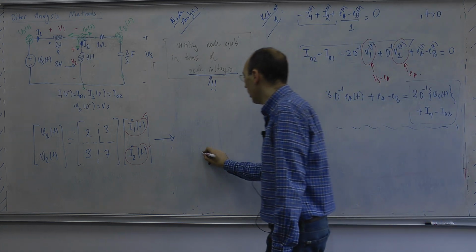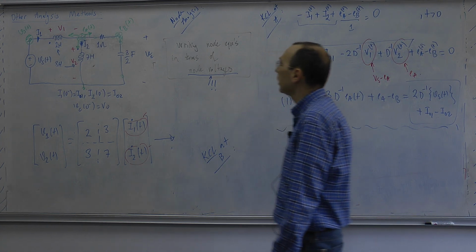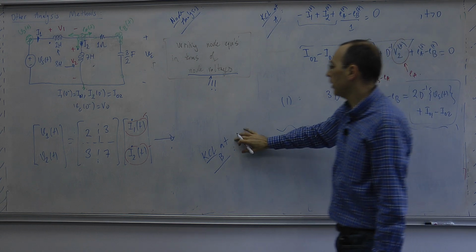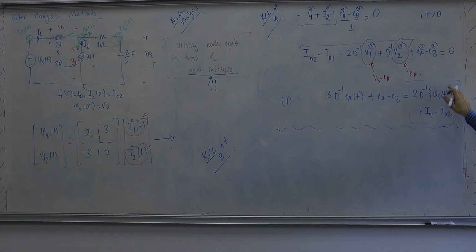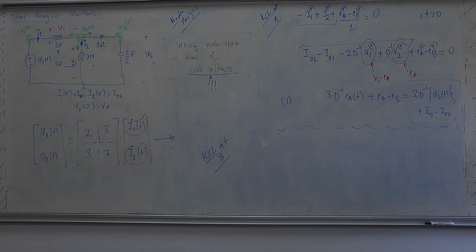So let's see, KCL at B. Again, I have two unknowns, so I need two equations. And you'll see that this will be an integral differential equation because there is the inverse already appearing over here. KCL at, well, not actually, because this is a known function. So this known function's integral is something known, this is another forcing term. But due to this actually, due to this we have an integral differential equation.